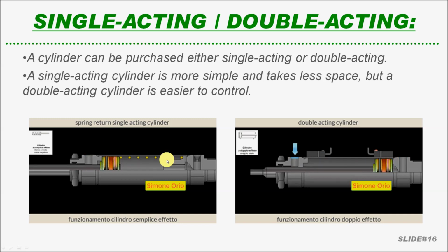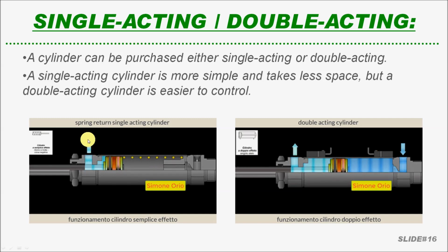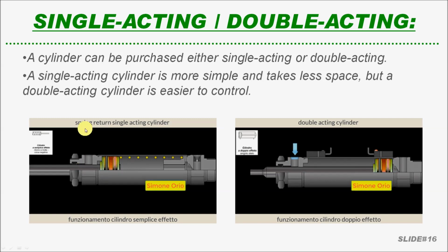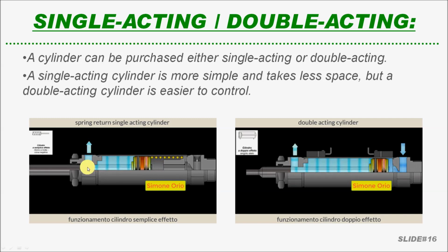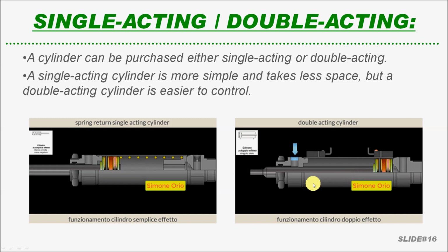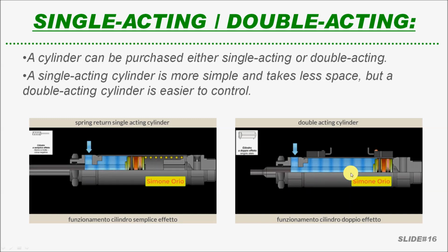a single acting cylinder where you use a spring. So you energize the piston and you exhaust that same port to the atmosphere and the spring pushes it back. So a lot of times this is more convenient than this, but sometimes you need a little bit more precision on your actuation, and this may be a better option.